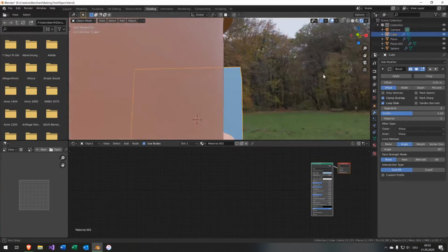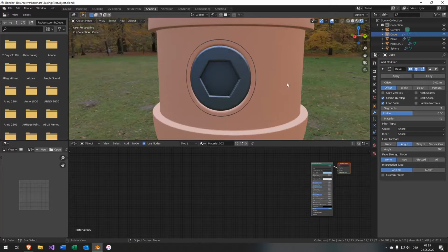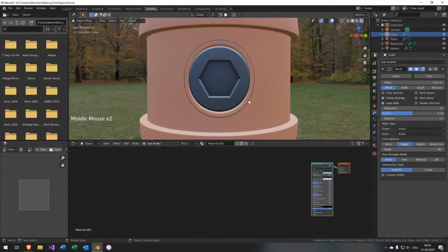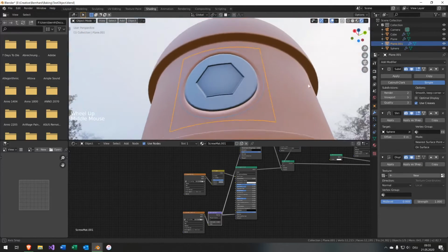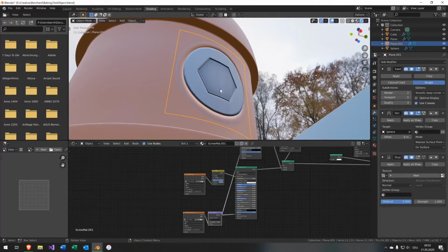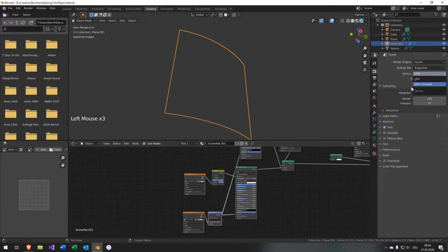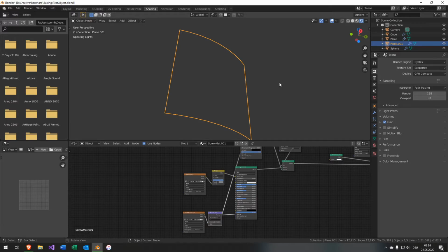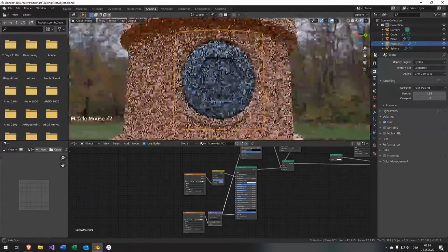And now I can see some small problems with shading. We have some edges here due to the subdivisions we made. It's pretty hard to see, but in this case it's slightly visible. On other occasions this is even more visible and can't be ignored or overlooked. So first thing we're going to do is let it render in Cycles to get a better view of this.